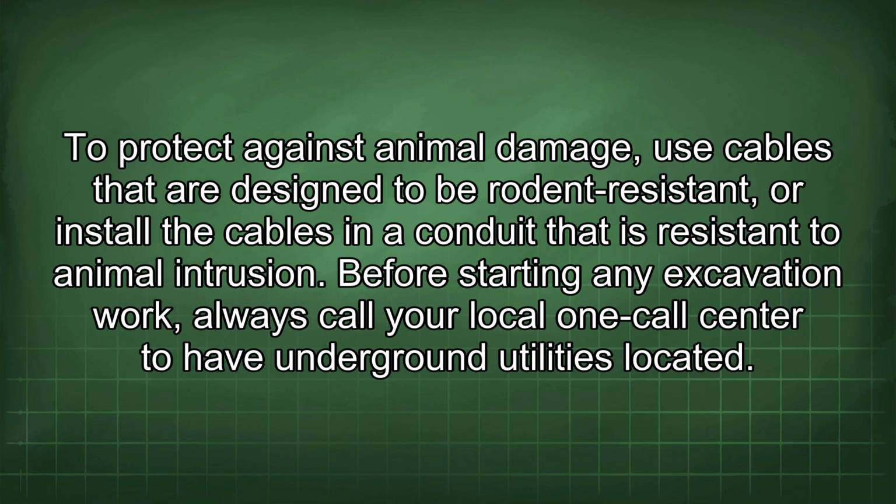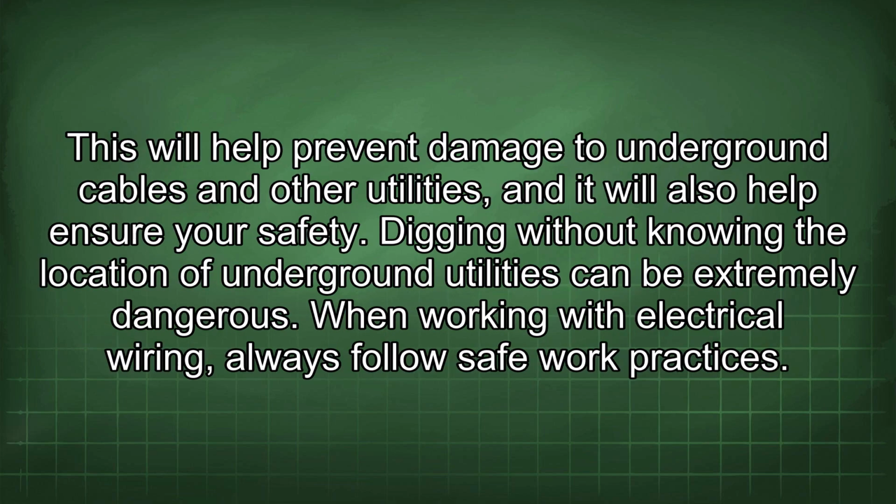Before starting any excavation work, always call your local one-call center to have underground utilities located. This will help prevent damage to underground cables and other utilities, and it will also help ensure your safety. Digging without knowing the location of underground utilities can be extremely dangerous.